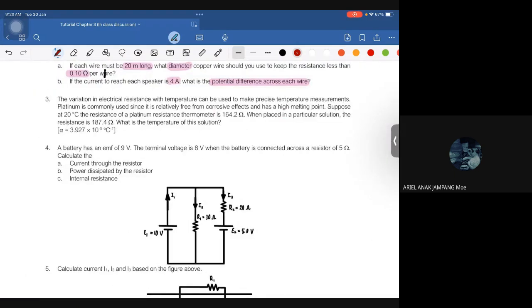We have, this one is on the subtopic variation of resistance with temperature. For this one, if it gives the temperature coefficient of resistivity, which is alpha here, you directly apply the formula R equal to R naught 1 plus alpha T minus T naught. I think the other day I mentioned that this one is the final temperature, and that one is the initial.